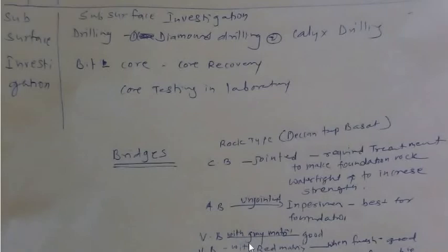to the atmosphere. That means after excavation, at the time of foundation, immediately cover this. Don't allow this volcanic breccia with grey tachylitic matrix to be exposed to the atmosphere, because it behaves like amygdal basalt, a good rock, but don't allow it to be exposed. Then volcanic breccia with a red tachylitic matrix: when it is fresh, it is good. On exposure, deterioration of this red tachylite takes place. Therefore, you can take the foundation of a bridge on this tachylite when it is fresh.